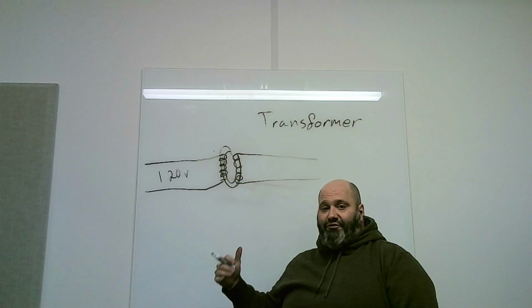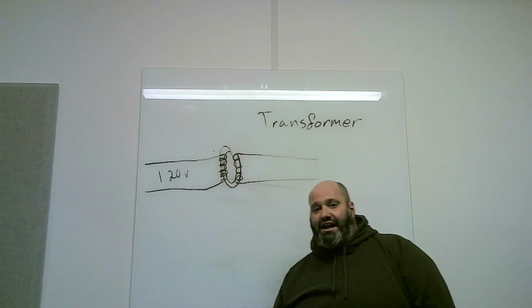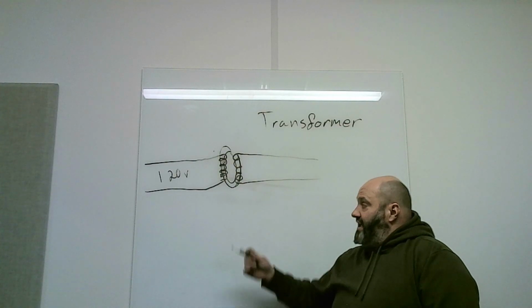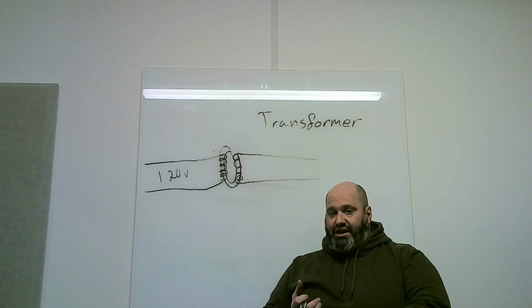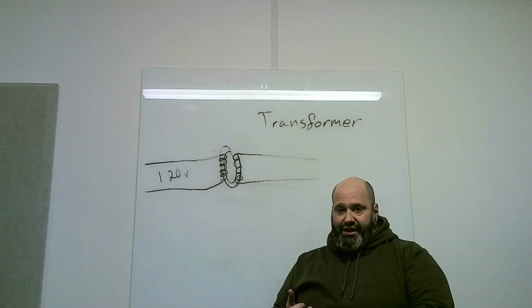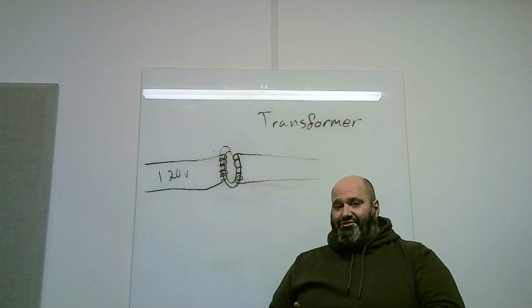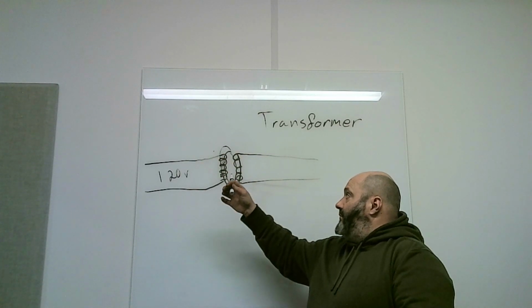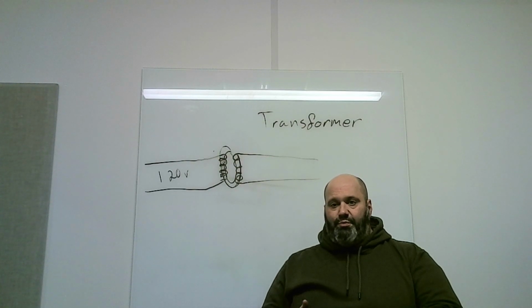That electromagnetic field then actually generates the current in the secondary side. Then that current flows through the induction coil in, say, your contactor or a fan relay, and then will open or close that control based on what the transformer is sending and what other control switches are opened or closed.